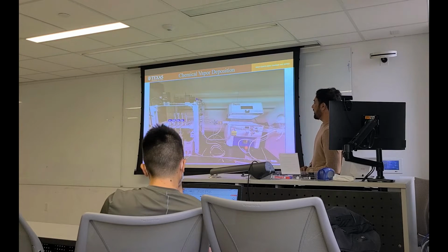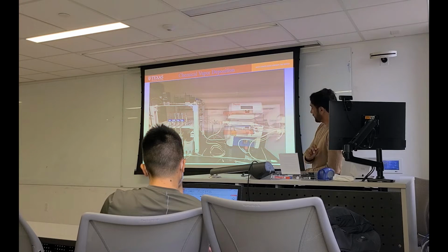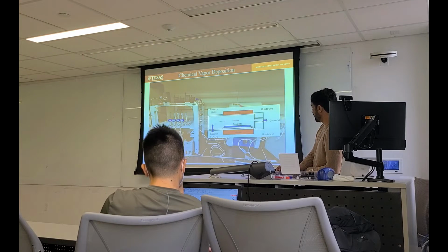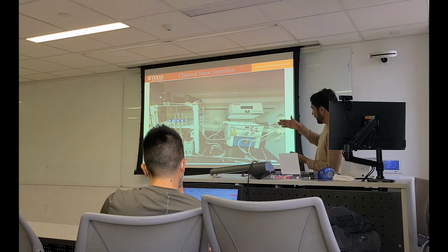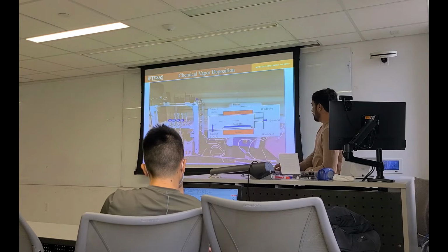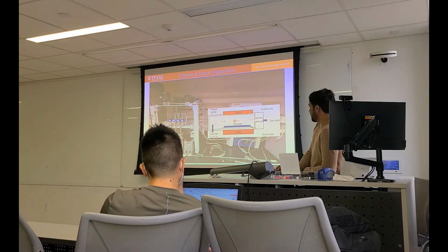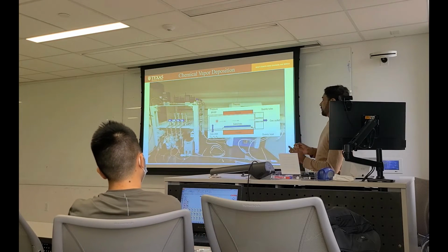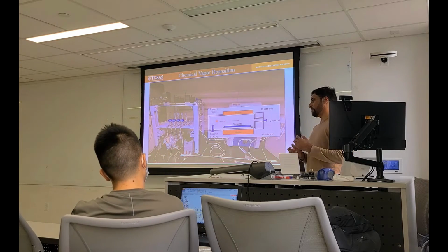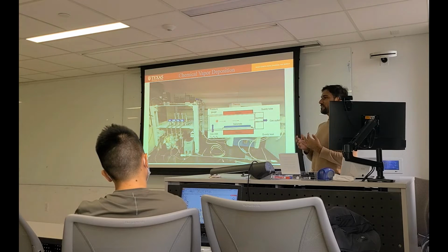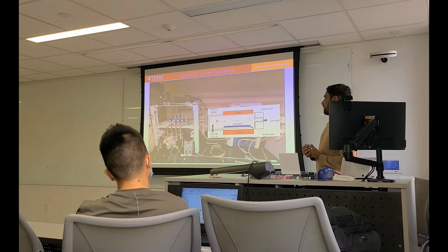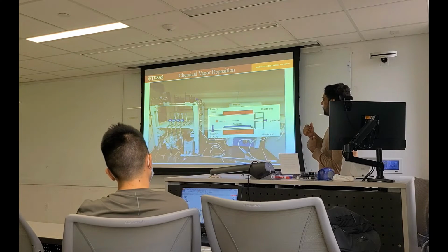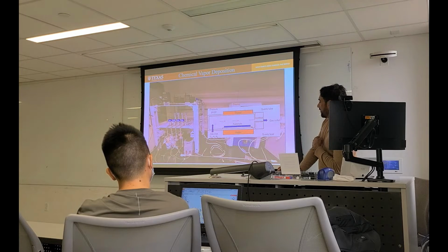This is also a horizontal reactor. So the issues with the horizontal reactor, if you see there, this is your substrate. The heater is in this panel and in this panel. They close it and then the heater is right around the quartz tube. So when gas comes, there are different temperature zones. It is very difficult to optimize the flow rate because each precursor has a different density, different mass, different weight. So you have to tune your flow rate uniformly. The other issue is that their sources are solid sources, metal sources.